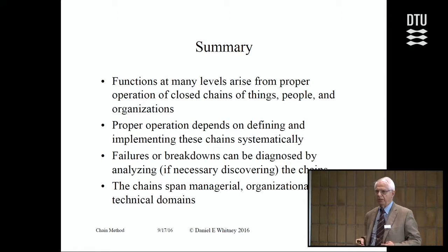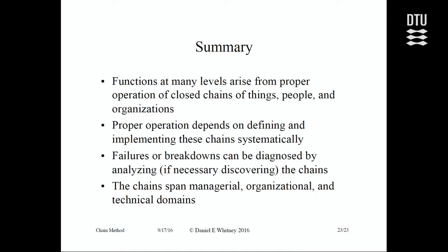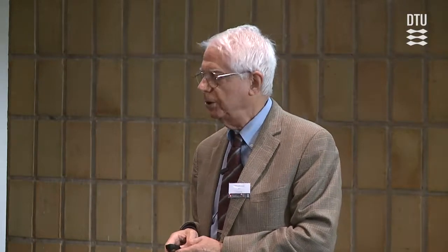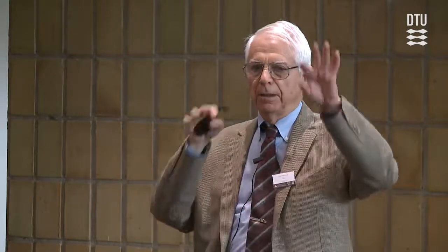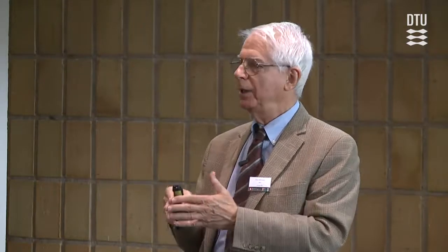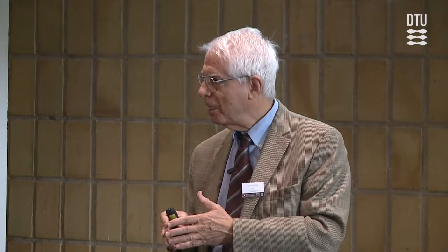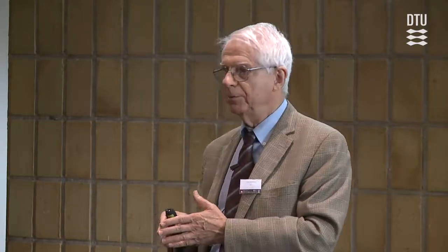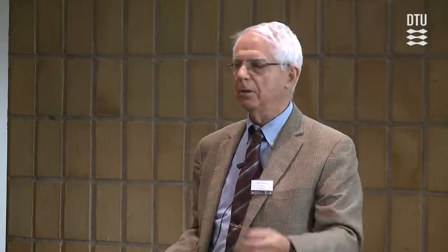What I would like to see in mechanical design is that part of the design is this chain. Put the chain on the top drawing. Make the chain part of the design review process. What is your key characteristic? What is your chain for delivering that key characteristic? Have that question come up at every design review. Do you know what you're doing? When you get done, you have the design intent documented, and it's been scrutinized, it's been critiqued by other people in the design review. If something goes wrong, at least you know where to start.